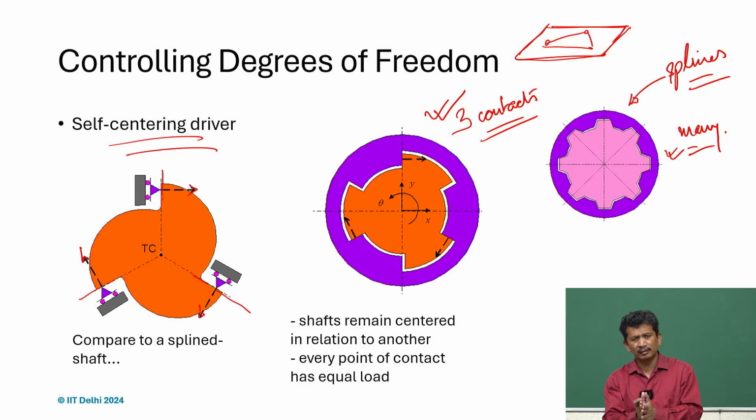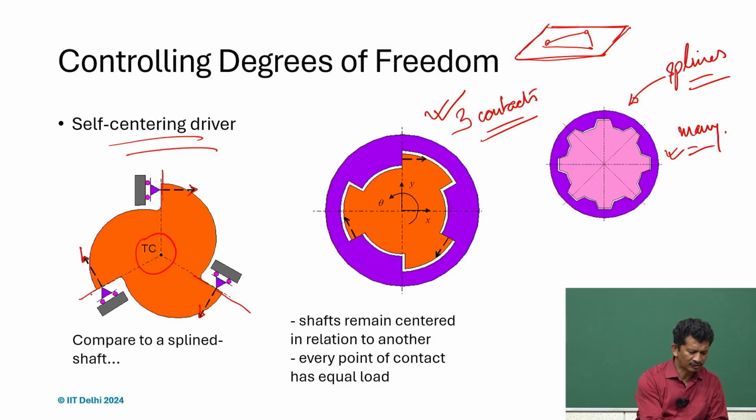So, again it is a constraint, a linear constraint away from the center, and there is also a concept of thermal center. What you realize is that if there is any differential change in dimension, either contraction or thermal expansion, this thing will simply slide. That is why you see the rollers here. It will not provide any kind of over constraint. It can easily slide, but what is important is that this point will be invariant.